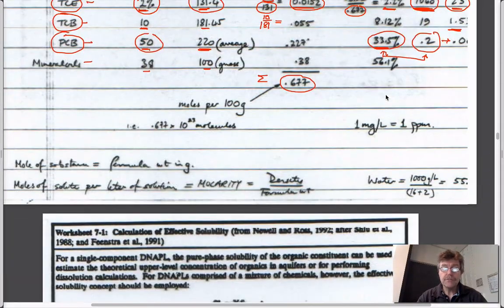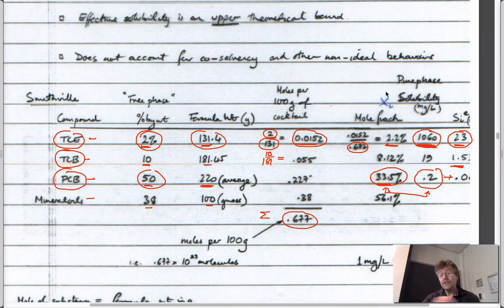So I guess the other thing is, if you now take a sample out of an aquifer, and you find that the aqueous concentrations within that sample, for this particular cocktail going in, were larger than 23 parts per million, say they were 100 parts per million, the conclusion that you might come to is that it can't really get to that. And so that's one way that you have for being able to say that potentially the only reason that it could be higher than the actual solubility limit would be if it's there as a free product.